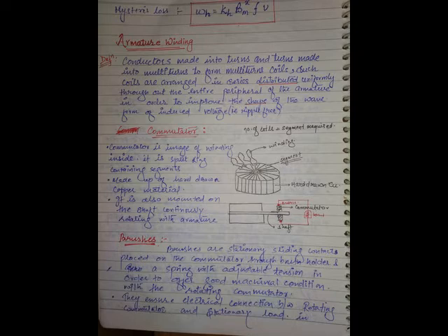That is one thing. But the second one is, I made you change the color of the pen right on the statement. MNA, do you remember? Magnetic neutral axis. Brushes are always placed on the MNA for the commutation to be successful.